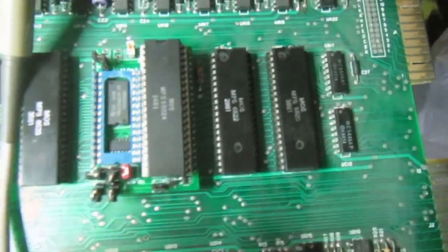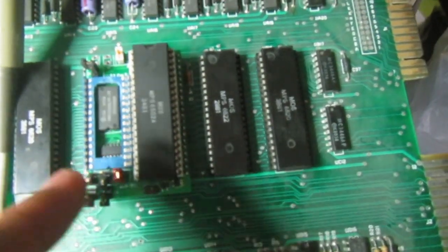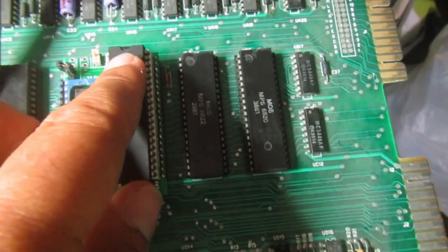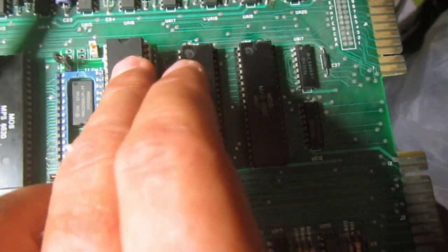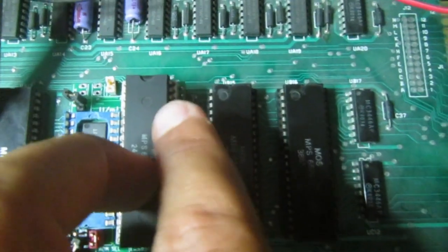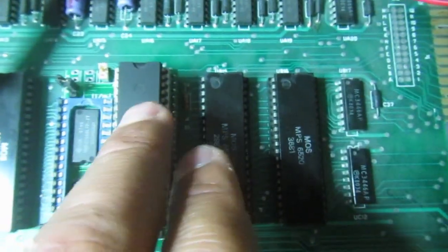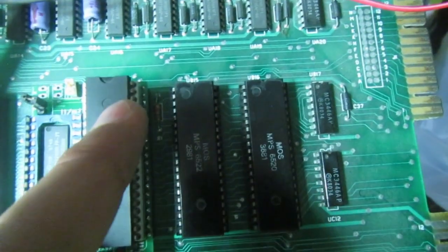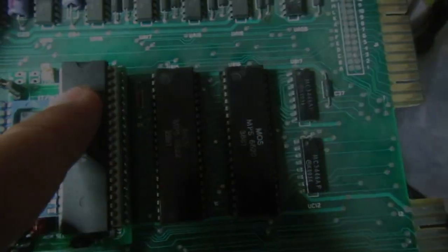Okay, as you have seen on almost all other computer repairs, I always check the reset signal to the CPU, which on a 6502 is on pin 40. It should be low for 1 second or so before powering on, then goes high.